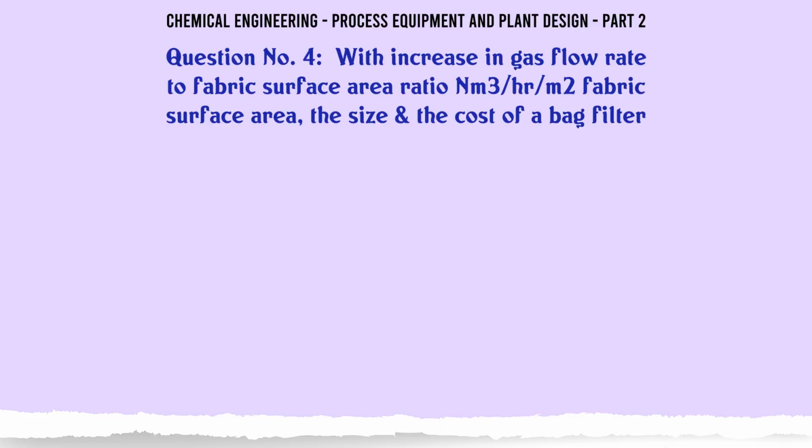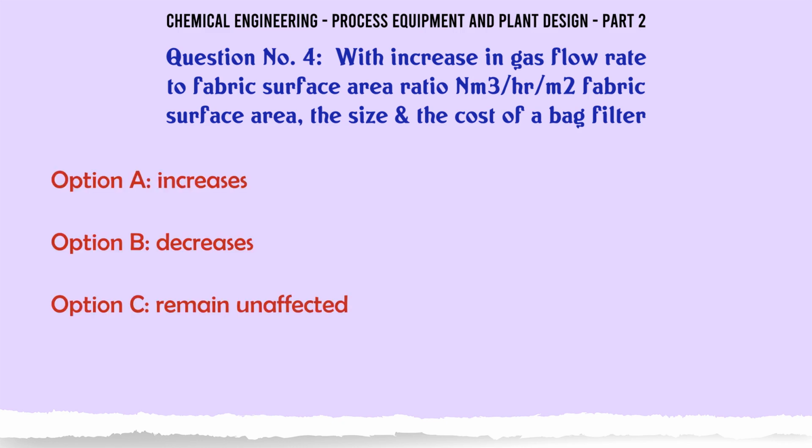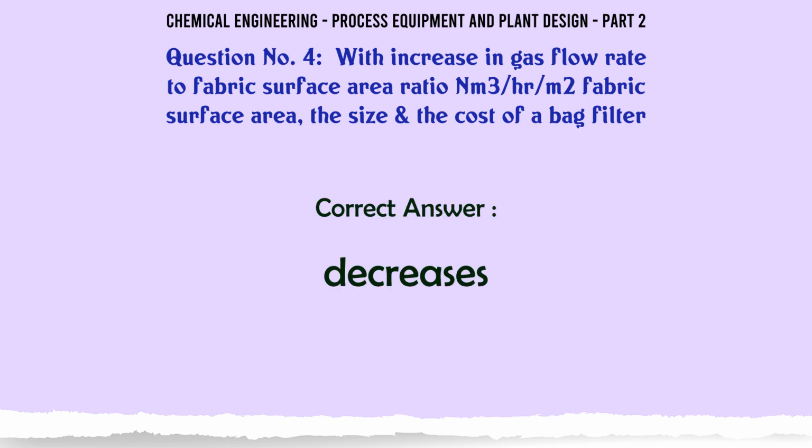With increase in gas flow rate to fabric surface area ratio, Nm3/hr per square meter of fabric surface area, the size and the cost of a bag filter: A. increases, B. decreases, C. remain unaffected, D. none of these. The correct answer is decreases.